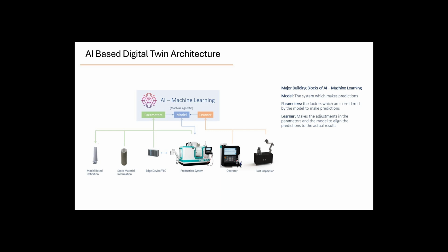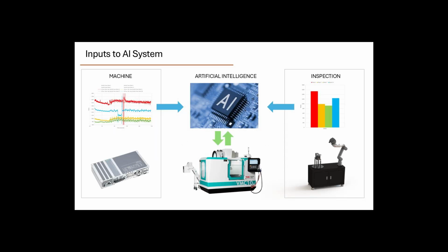So this is one of the reasons why you want to take any measurement that you can on your stock material before it goes into machining, because those data points really help to understand what's going on. You can take a 3D scan of it. If you can get a quick temperature measurement on it, any amount of measurement that you can digitize and provide to the AI machine learning system that you see there up top is beneficial.